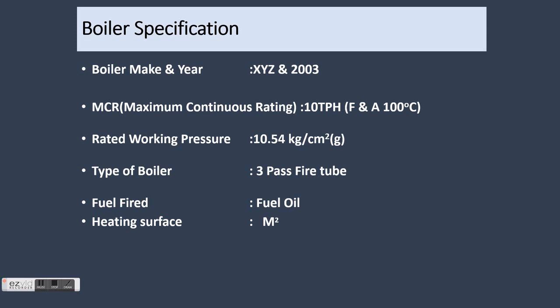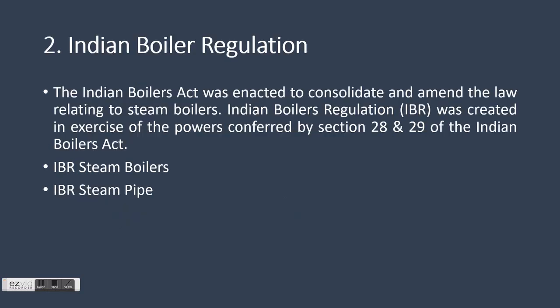Next is the Indian Boiler Regulation. The Indian Boilers Act was enacted to consolidate and amend the law relating to steam boilers. Indian Boilers Regulation, IBR, was created in exercise of the powers conferred by Sections 28 and 29 of the Indian Boilers Act. IBR steam boiler means any closed vessel exceeding 22.75 liters in capacity and which is used expressly for